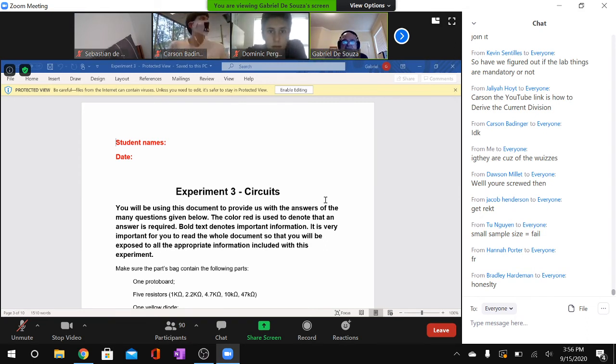For every current measurement, you have to break the circuit, because what you're measuring is what is flowing through the wire. So always make that differentiation. Current, you measure what is going through the device. Voltage, you measure what is across the device.